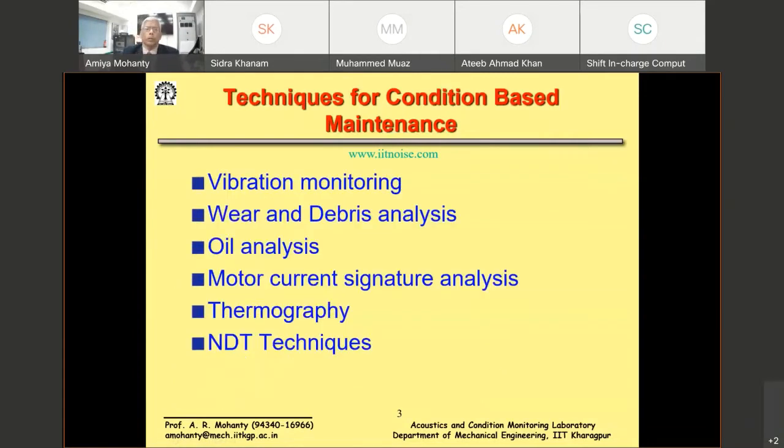So the existing techniques, some companies will be only doing maybe vibration monitoring of the machines. They will have an equipment, they will have a transducer, measure the vibration, find out the physics-based reasons why, what kind of problems is there. If a machine is rotating, it is having shafts which are supported on bearings.